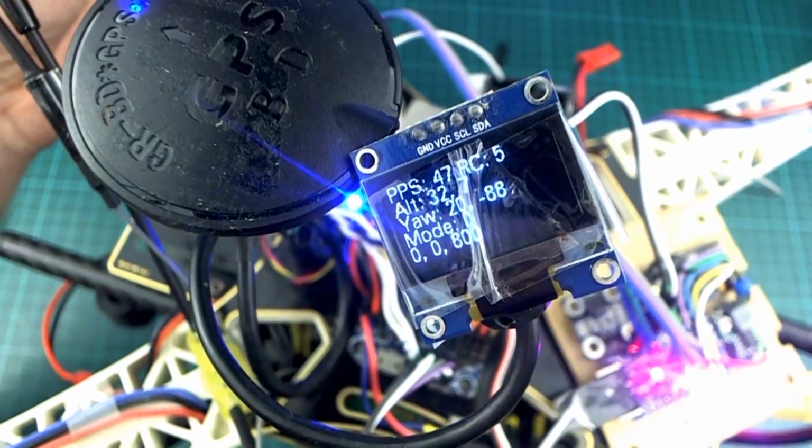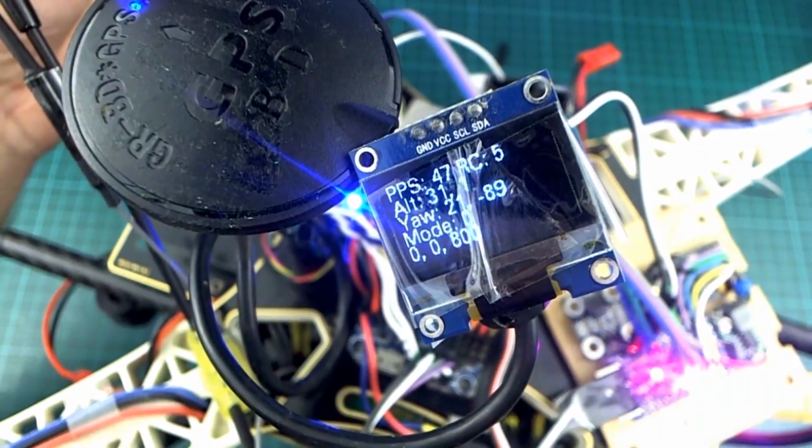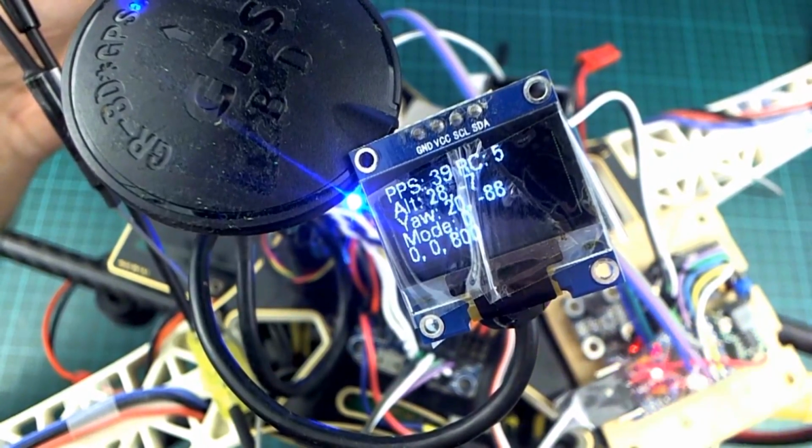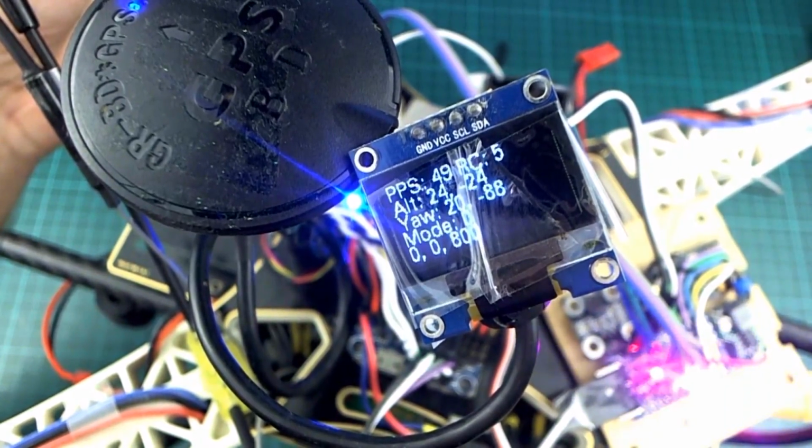And the important point to note here is that when you turn each of these on, they should be at the same altitude so that they both record the same altitude as 0, because in some of the flight modes, the quadcopter will try and put itself at a certain altitude above the tag. So if they're not both started at the same altitude to record 0, it might not work out too well.